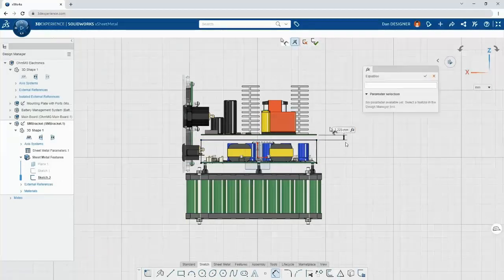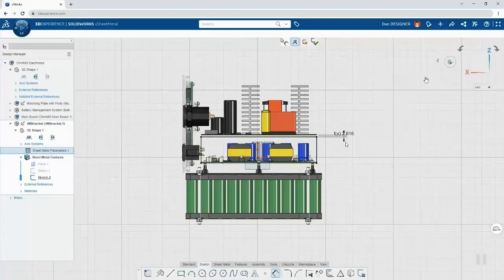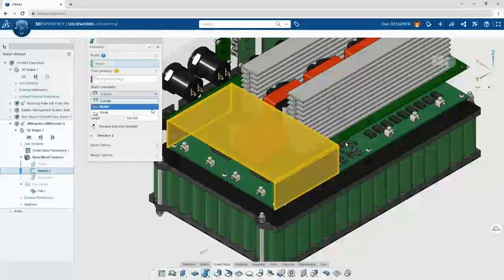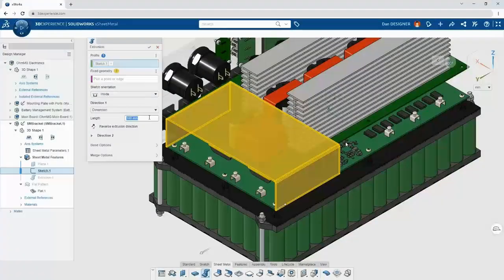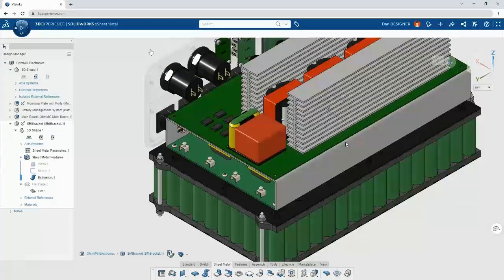So, in order to create a part in assembly, it's very simple. You can insert a part into the unified environment and just start modeling. In this case, we're going to start drawing around the other parts and referencing them to create a sheet metal part in here. We're going to dimension it away from other parts and set the thickness equation here.